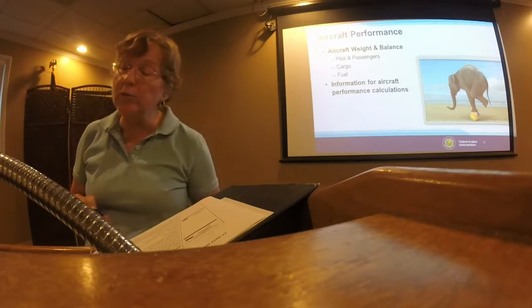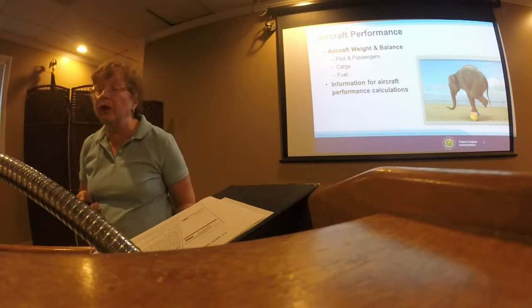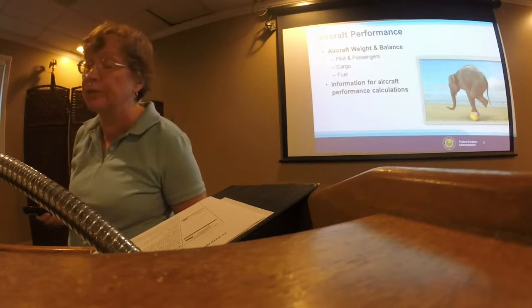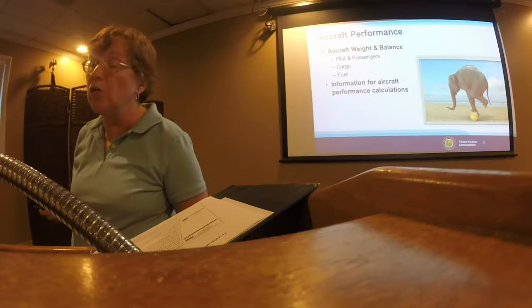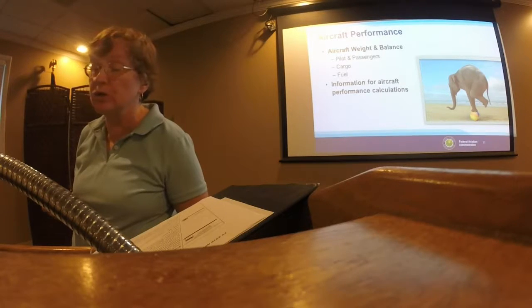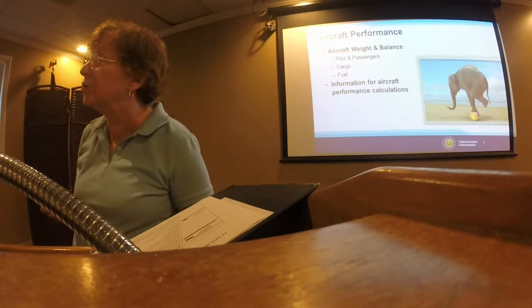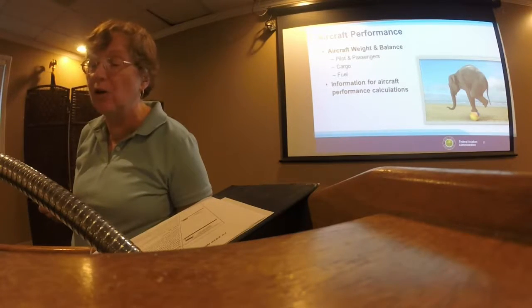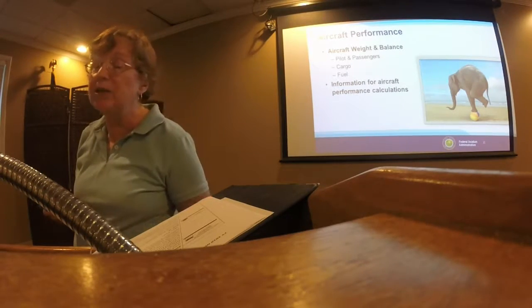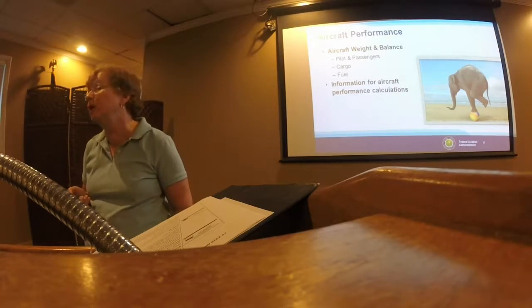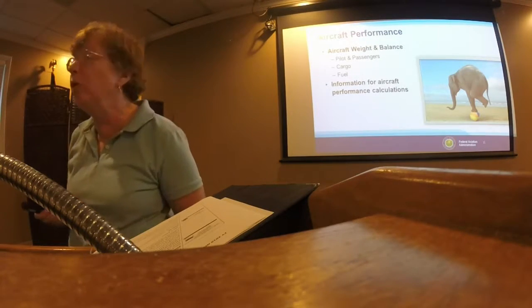So a recommendation of a way to plan a flight is to decide how much weight you want to haul to what destination. Start with your crew and passengers, then whatever you want to take along as well, the cargo, the bags, the golf clubs. And if these items alone exceed your aircraft's capability, you'll either have to make multiple trips, leave the golf clubs, or get a bigger aircraft.